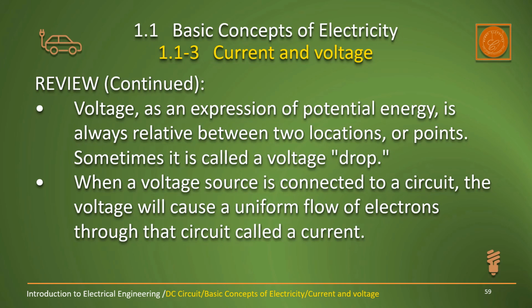So if you are doing electrical work in the future, you will often need to calculate the voltage drop to decide the cable size, the wire size. Normally, according to the standard, the cable voltage drop should be less than 5%, or in a company, we use 3%.